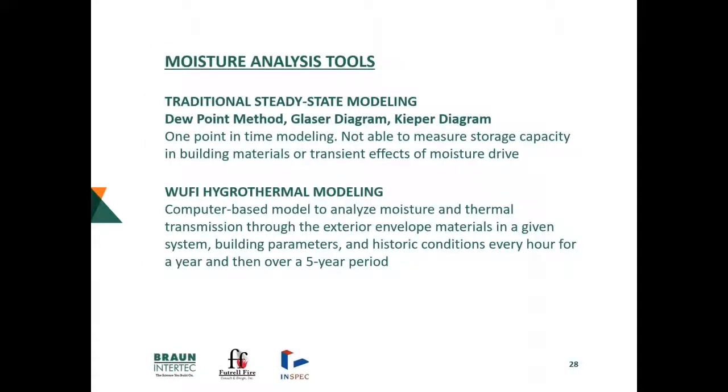We use a number of tools. Mostly we zero in on the WUFI hygrothermal modeling tool to understand moisture accumulation in our assemblies as we evaluate for folks that want us to do peer review work, and obviously evaluating our own designs as well. Steve talked a little bit about the traditional steady state modeling, the psychrometric chart. That dew point method is what we kind of grew up with, but it's really only one point in time modeling, and it's not able to really measure the storage capacity of moisture in the building system.